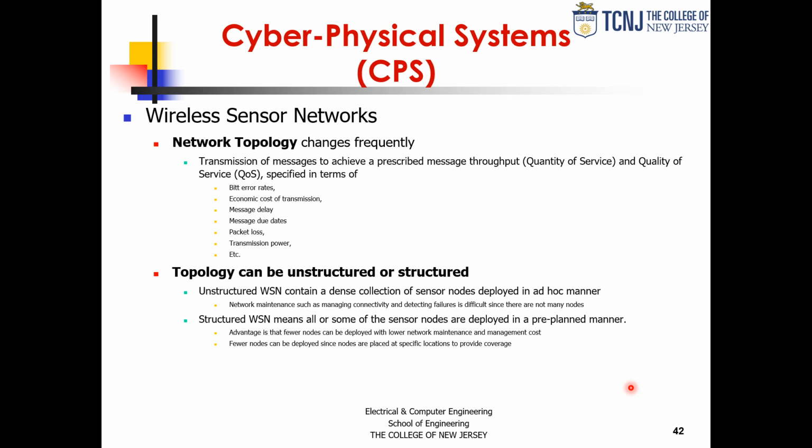So in a sense, it's more expensive from a complexity perspective to deal with an ad hoc network, but it really gives us a lot of flexibility, and it really goes well with these wireless sensor networks, which the end application of them can vary a lot. So what you see is that in wireless sensor networks, ad hoc connectivity is not only a plus, but almost a must. And there are standards such as Zigbee and Bluetooth that have certain ability to form ad hoc networks as part of their specification.